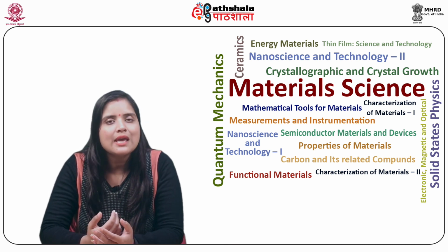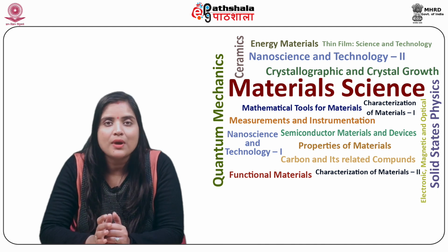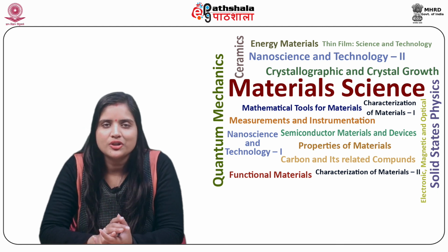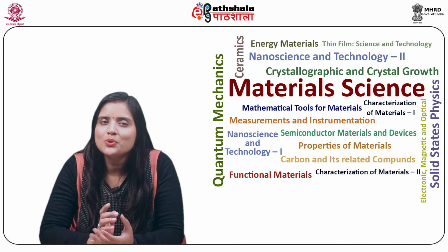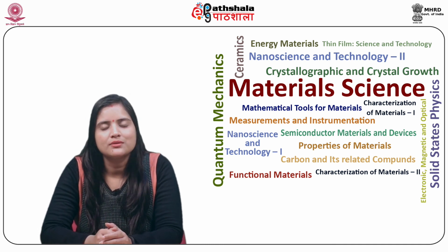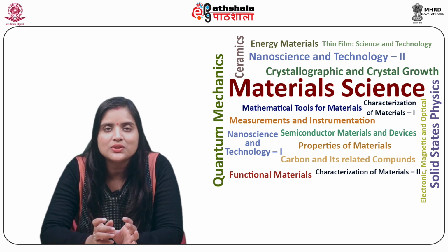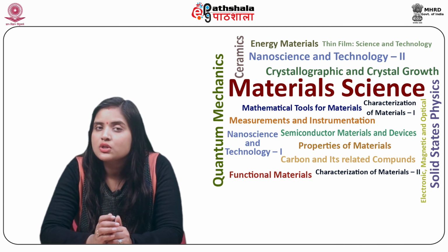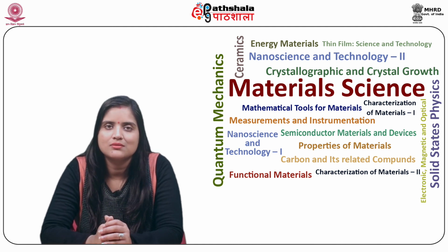Let us now study the applications of ball milling. Ball milling is extensively employed to grind materials like coal, pigments, and feldspar for pottery. Both wet and dry grinding are possible. However, wet grinding is usually done at low speeds. Ball milling increases the solid-state chemical reactivity in multiple component systems. Furthermore, it can also be used to produce amorphous materials.